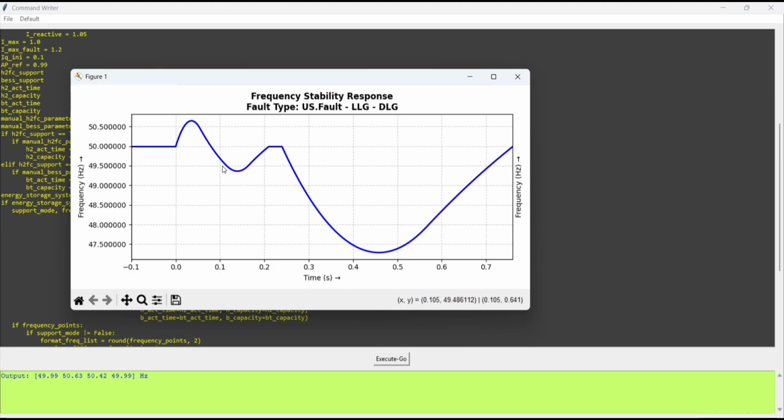spike, an initial small frequency dip is observed. Then after that the battery energy storage starts actuating its control and recovers the frequency, but after applying the power up to a certain time, its remaining capacity ended, meaning the 0.5% charge, the SOC, decreased and it hits the minimum limit of 20%. So the battery logic stops the battery power supply, and at that time as wind turbines or